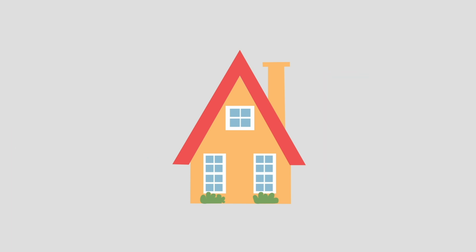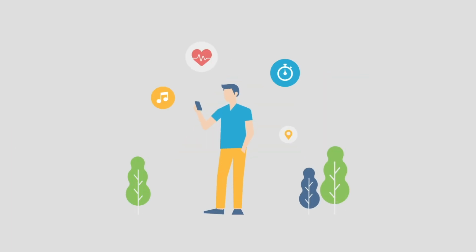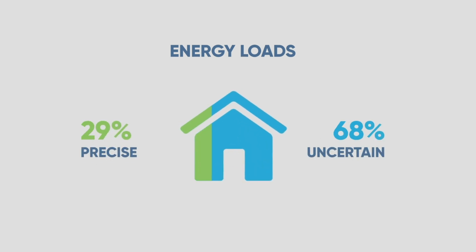Here's the reality check. Space loads depend heavily on occupant behavior, making this one of the most subjective and uncertain parts of energy modeling. Material properties are precise and measurable, but how do you accurately predict human behavior 8,760 hours a year? Will people arrive at the same time every day? How many will there be? What activity level? Will they turn off lights or plug in extra devices? Before you get discouraged, keep these important points in mind.